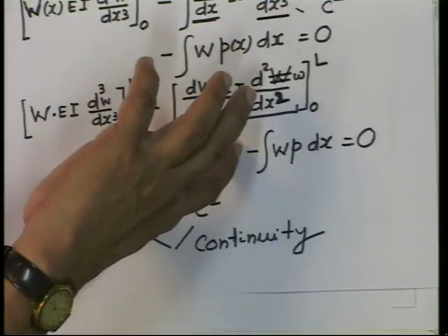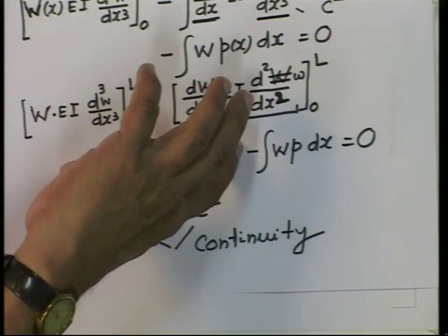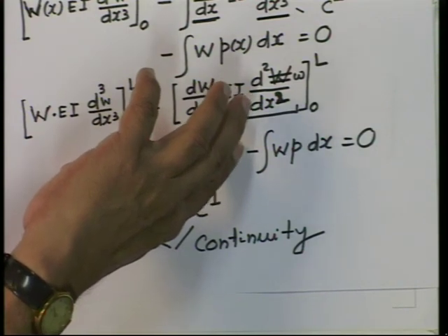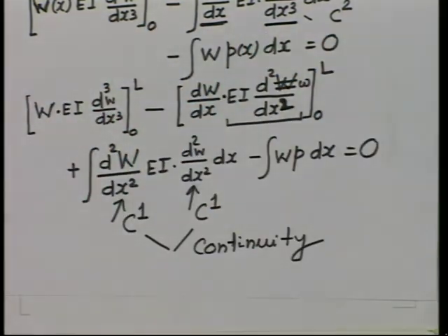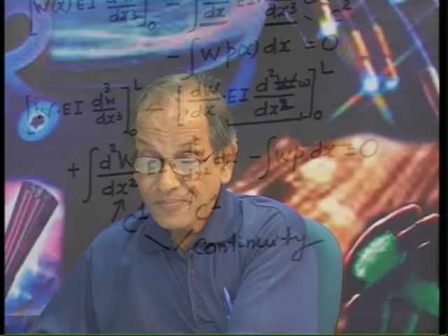So, we stop here. This is my integral; load integral, there is no problem, but this is the basic integral. Actually, this one will give you your K stiffness property, this one will give you the load term, and of course, these are the boundary terms. We will see how to deal with this C1 continuity. All the problems of beams, plates and shells are C1 continuous.